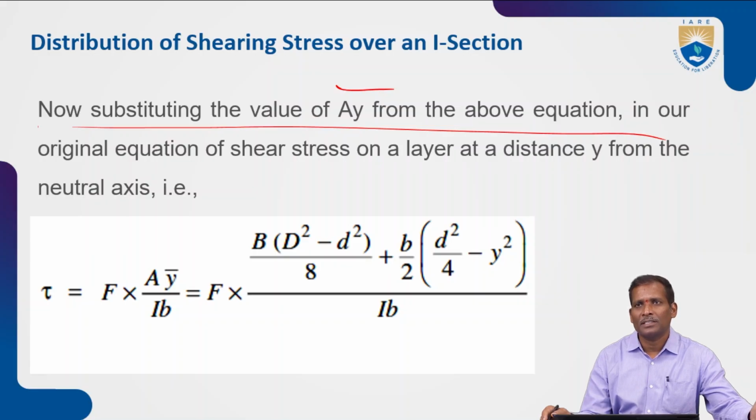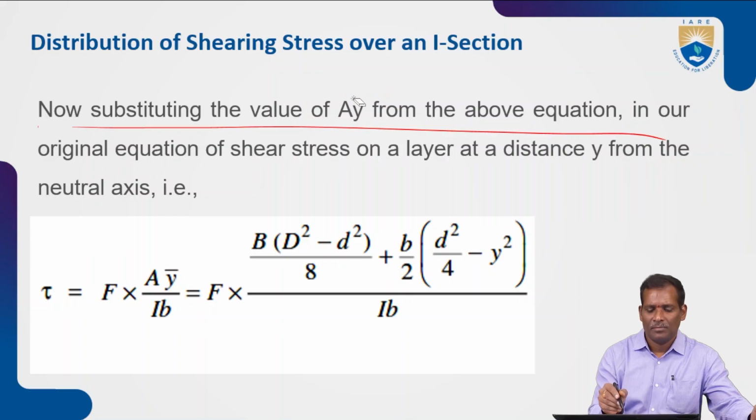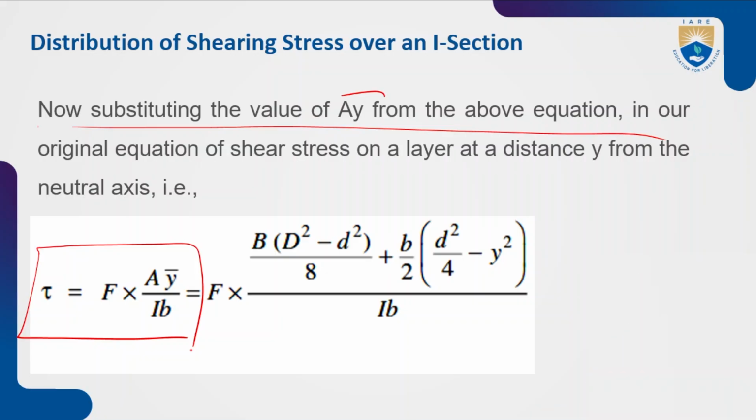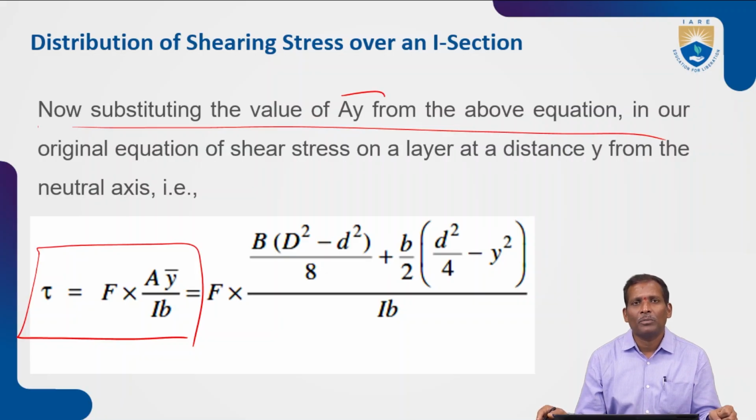on a layer at a distance y from the neutral axis. So thus, shear stress is equal to force multiplied with A y bar by Ib.